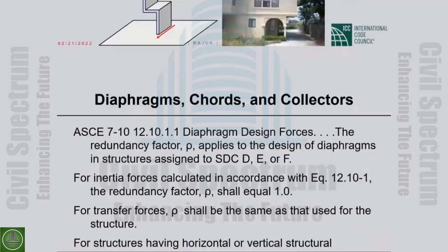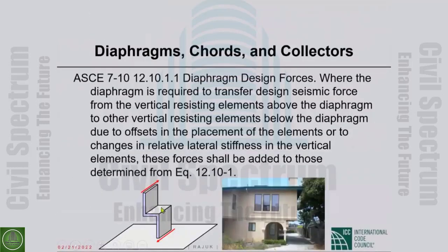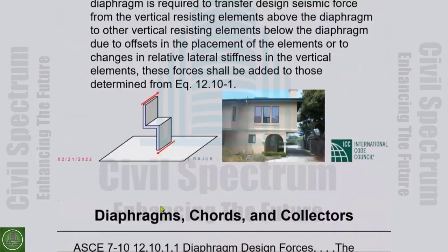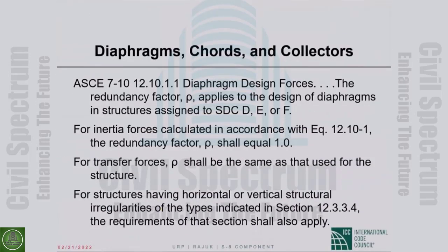If the lateral forces you are transferring are seismic forces, then the earthquake effect will include the rho factor, and the earthquake effect will then be combined with the gravity load effect through the load combinations.